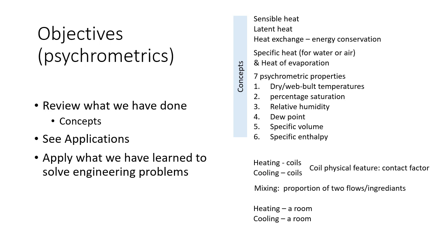So when we supply warm air into the room, we provide sensible heat to compensate for heat loss in the room to maintain a comfortable temperature in winter. Similarly, in summer, we supply lower temperature air into the room and allow it to rise, so the incoming air absorbs heat to avoid the room temperature rising. This is where we remove sensible heat.